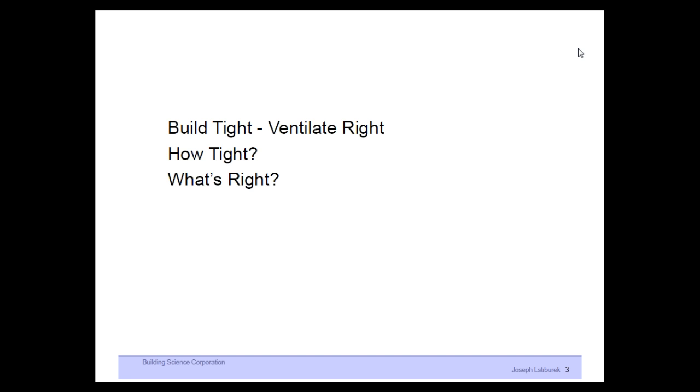From Sean's work, as well as other work that has been done by Canada Mortgage and Housing Corporation, Duncan Hill's work, and some of the RDH work in Vancouver, we're pretty clear that the 0.3 CFM per square foot at 50 pascals is a reasonable, achievable metric that results in significant tightening of buildings.